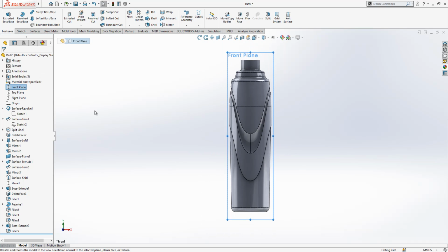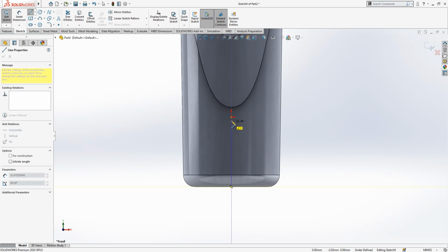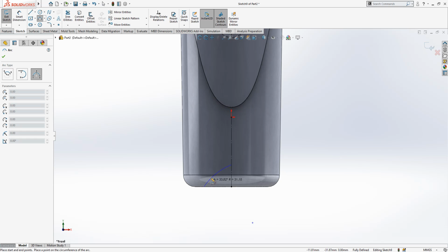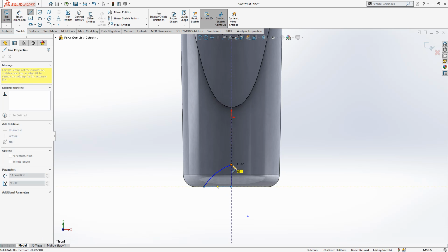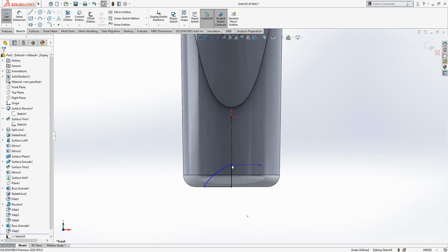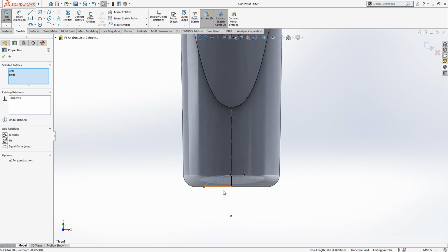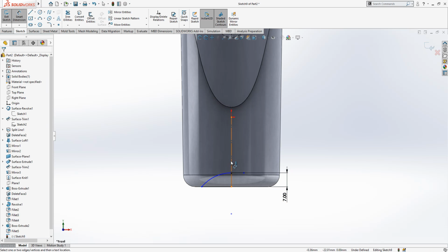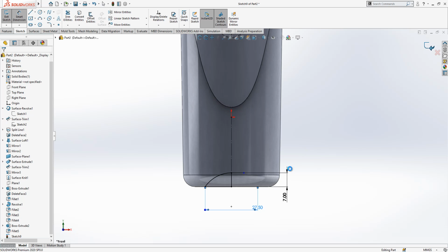In the front plane, I will create another sketch. Here I will create one line. Then I will create this arc. Okay, then I will do something like this. Close this one and convert this to a construction geometry. This is tangent. Height of this 7. Okay, if you select the center line and a point, you can define also diametral dimensions. Okay, we created this. It's okay.